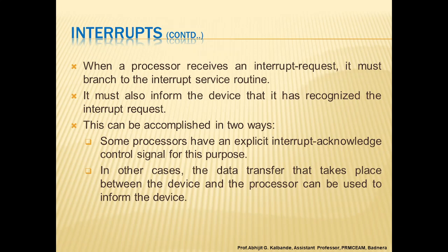A return from interrupt instruction at the end of the interrupt service routine reloads the program counter from the temporary storage location, causing execution to be resumed at the interrupted instruction. The return address is to be saved in the processor stack. Alternately, it can be saved in a special location.